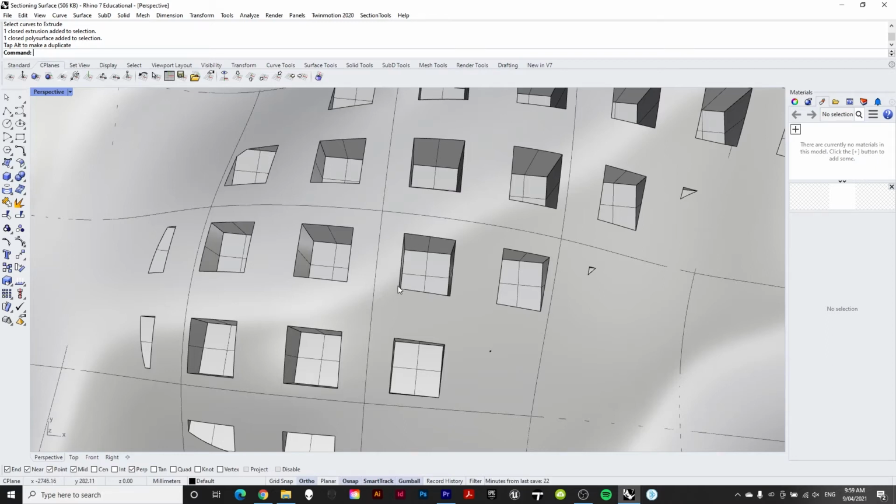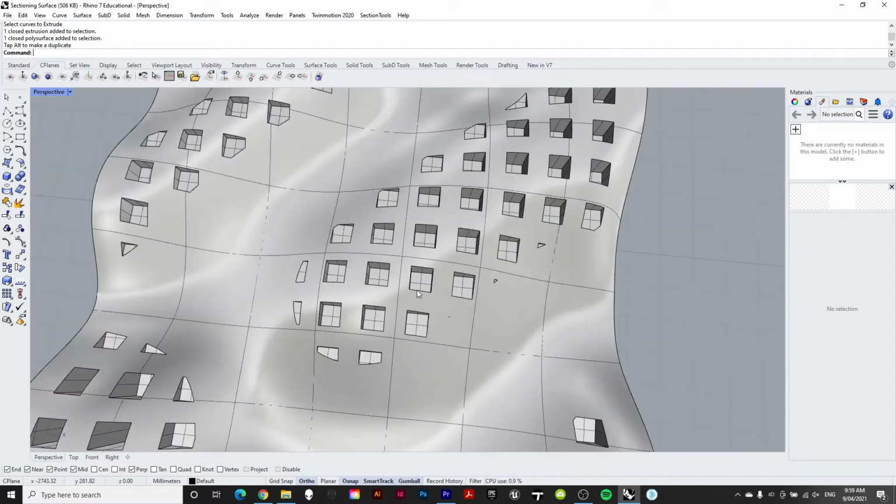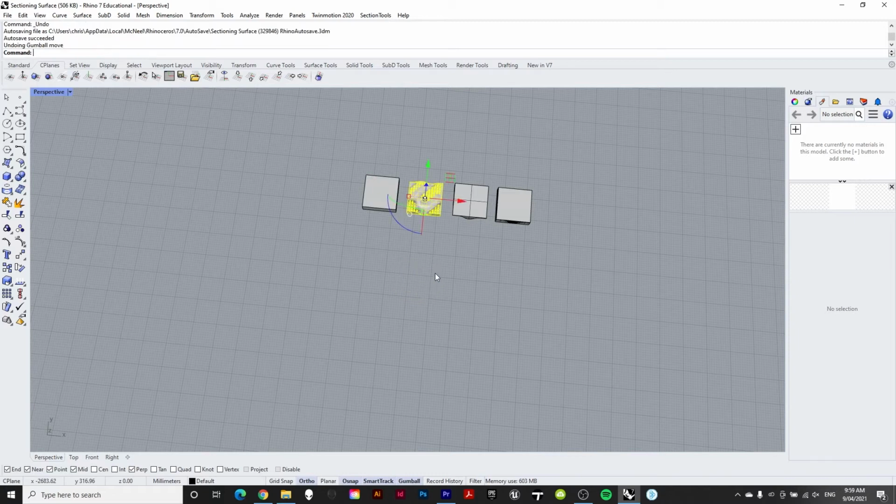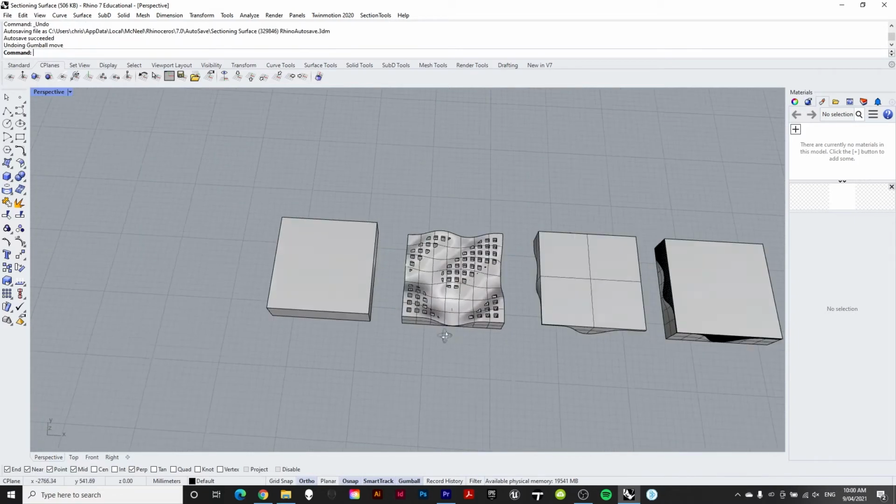So we need to be aware of the fact that these squares that we have here are going to have a radius to them. Now we can have smaller drill bits so that the radius gets smaller, but we're never going to get a perfectly square cut edge. So if that is an issue for you, potentially 3D printing again is a different or better option. Alright, so let's have a look at this in terms of what's actually happening.